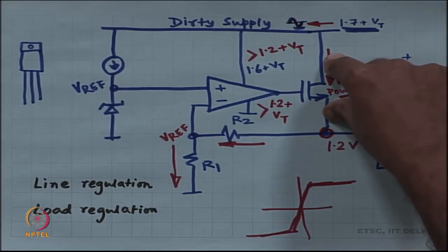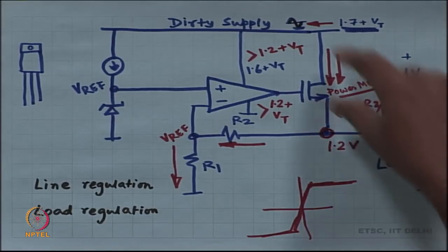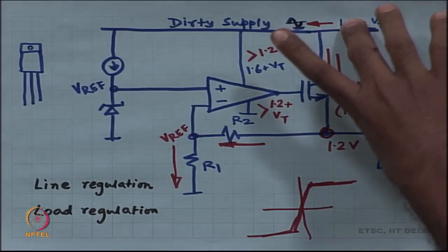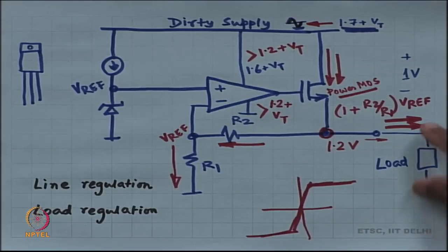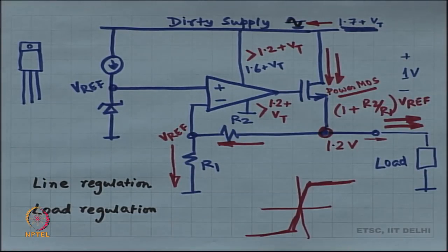What is the power used up over here? 50 milliwatts. 60 delivered, 50 used, net is 110. Okay. What is the efficiency? Efficiency is power delivered to the load divided by actual power drawn from the supply. So, that is 60 divided by 110, okay, it is less than 60%, right, and this is happening in the power supply. Okay, this is a disaster,